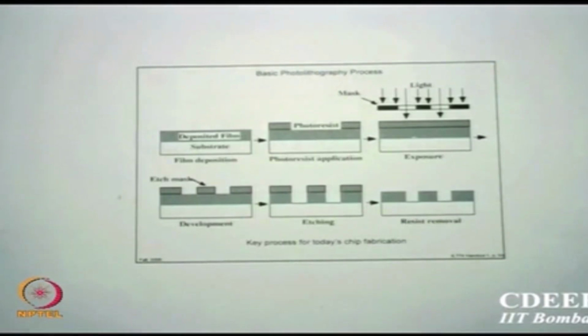So what does it essentially mean? Positive photoresists are generally resin materials which have long carbon cross-linking chains. Whenever the linking fixes itself into huge circular rings, it is called unetchable, bonding is complete. Whenever a chain breaks, you say it is etchable. So the PPR, positive photoresist, is initially hard, that means completely linked. Whenever light shines, photons are received and the links break. So that area will become soft, and soft means etchable.